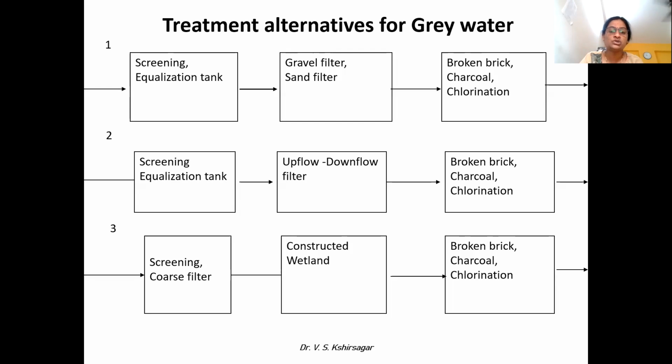soil, and in that soil you can put plants which have a high capacity to absorb COD, BOD, etc. Simply I can say, the plants of the canna (कर्दळी) variety; you must have seen canna plants. That kind of plants absorb a high amount of impurities from the sewage, and then the sewage will be allowed to pass into that particular area that we have constructed.